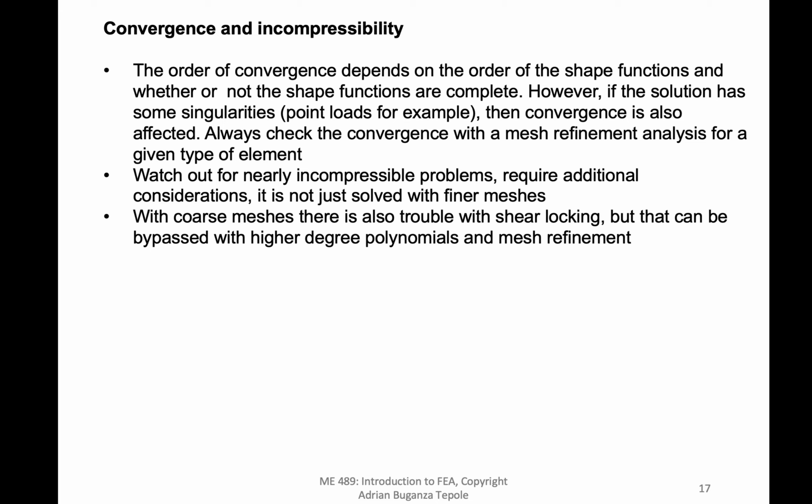So those are three things that you have to be careful about when refining the mesh. It's not all about refining the mesh. Again, you have to be careful about the fact that the solution, if it has singularities, even if you refine the mesh, you won't get the desired convergence. Another one is that if you have a problem that is incompressible or nearly incompressible, your solution will converge, but it will not converge to the correct solution.